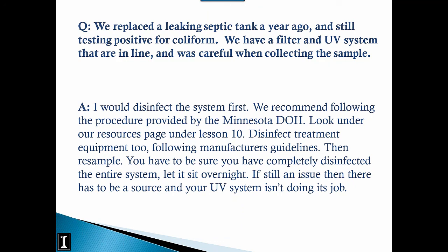And it could be an issue that it wasn't disinfected properly once everything was installed and everything was in place. So if you go to our webpage and look under resources, there's a list of documents that are freely available for each of the 10 lessons. And under lesson 10 is a well disinfection guide from Minnesota Department of Health. We've looked at probably 70 or more of those type of documents on how to disinfect your well, and we feel that the Minnesota document is the best one of all those. It's complete. It's got pictures.